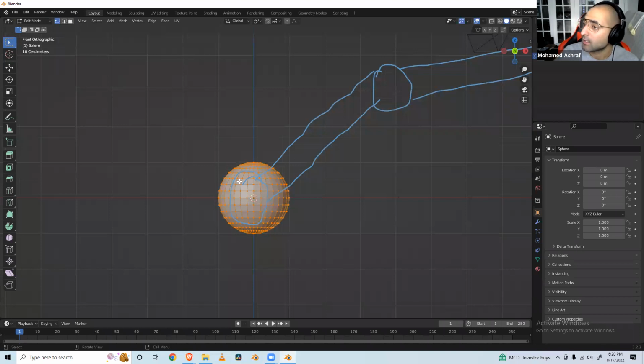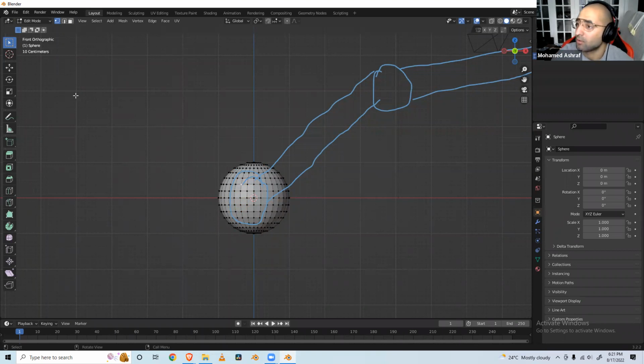Now this actually highlights every point, as well as every connection from one point to the rest. And we can select by point, 1, 2, 3, and we can manipulate point by point, which gives us a much higher level of control in edit mode as opposed to object mode. And it also allows us to shape this sphere the way we want to.